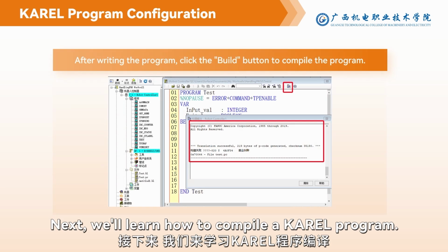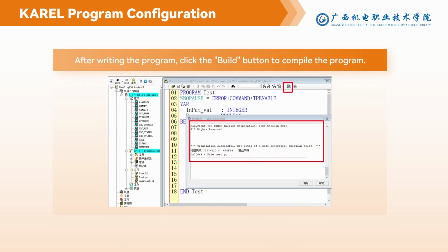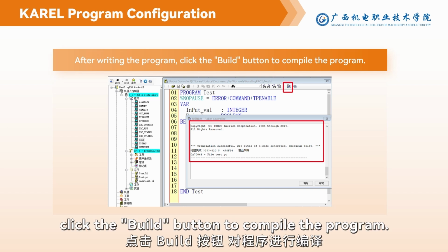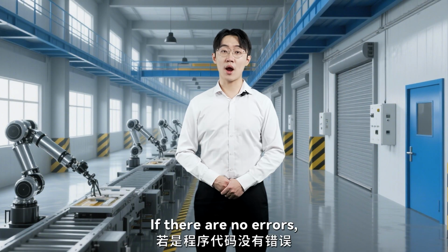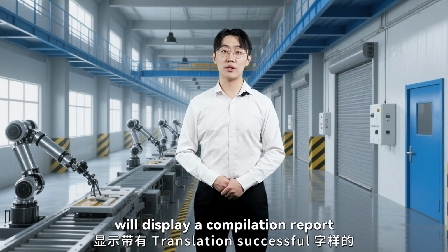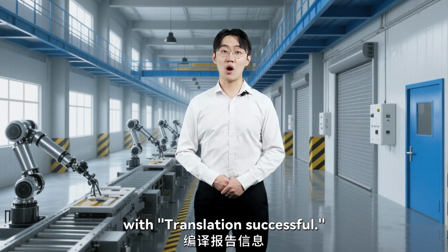Next, we will learn how to compile a KAREL program. After writing the program, click the Build button to compile the program. If there are no errors, the Build output dialog will display a completion report with translation successful.